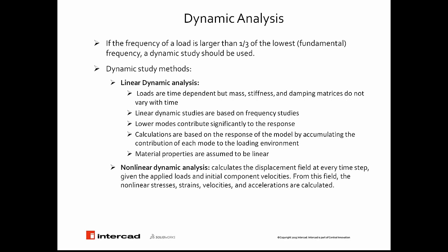In linear dynamic studies, loads are time dependent, but the mass, stiffness, and damping matrices do not vary with time. Therefore, such studies are based on frequency studies, and simply the first or lower modes of vibration contribute more significantly to the response of the structure. In such a study, calculations are based on the response of the model by accumulating the contribution of each mode to the loading environment.